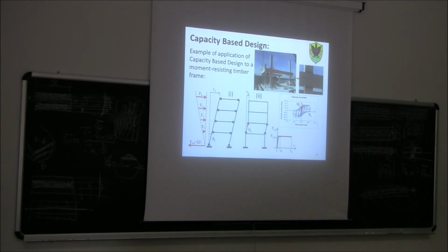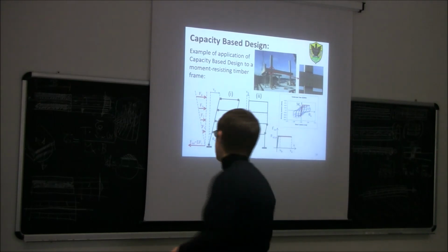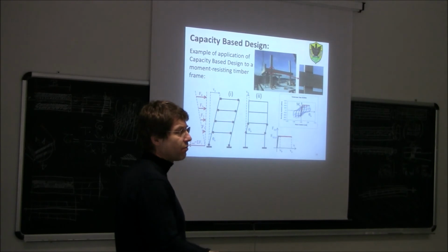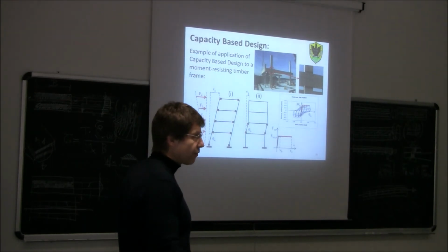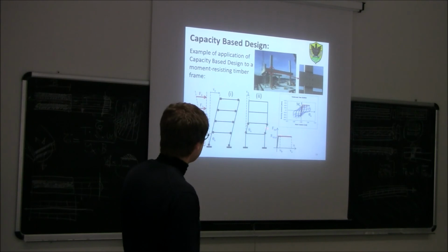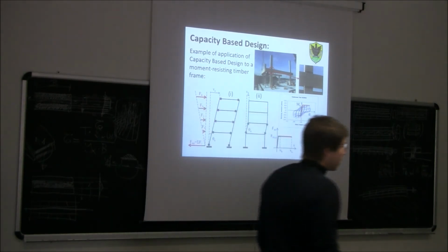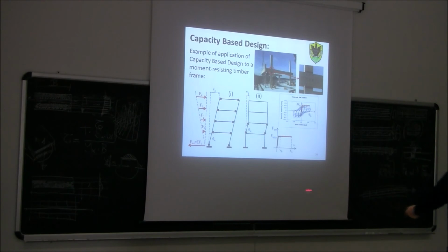with VB significantly lower than VA. Now, among those two different plastic mechanisms, we need to select the one that can ensure the maximum energy dissipation. If you think about having some cycles, it's clear that the second plastic mechanism, the storey plastic mechanism, will provide a much lower energy dissipation compared to the first one. So between the two different plastic mechanisms, we should select the first one, because the first one is the one that will bring us more ductility and more energy dissipation.